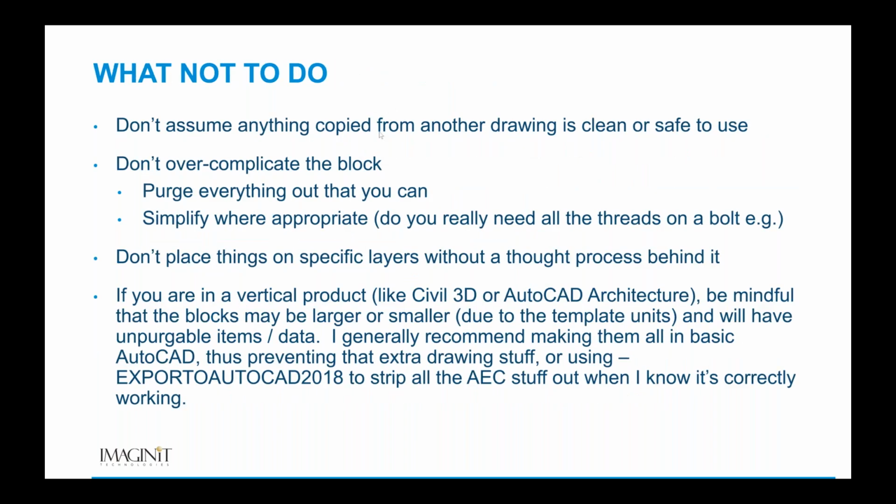What not to do. Don't ever assume that anything copied from another drawing is clean or safe to use. Don't overcomplicate the block. Purge out everything you can from the block. Simplify where appropriate. If you have a foot-long bolt and you draw threads on it, do you really need every single thread on the bolt? If you don't, simplify that down so it's just a rectangle.